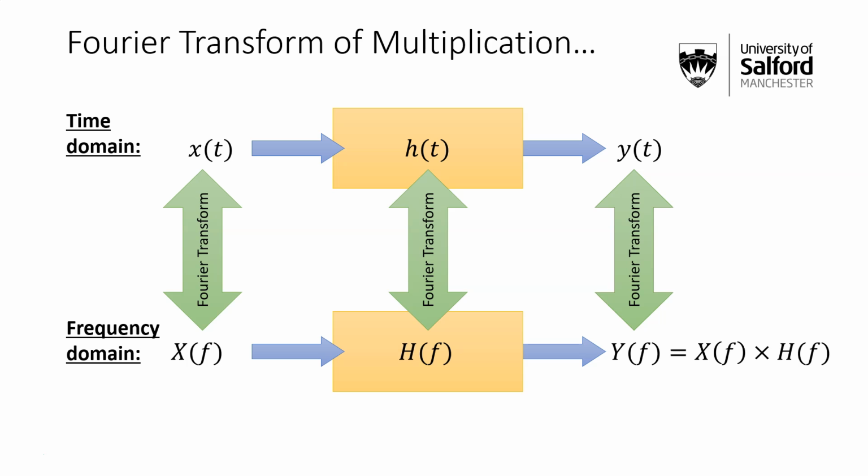The information in the impulse response, the response to the clap, or to get something louder, maybe a balloon burst or a starting pistol shot is what people might use to measure these things, is actually enough information mathematically to reconstruct y from x. And we know that because that's what the frequency domain told us. We have a statement in the frequency domain to get us from x to y via H, so it follows that we must have a time domain one as well.